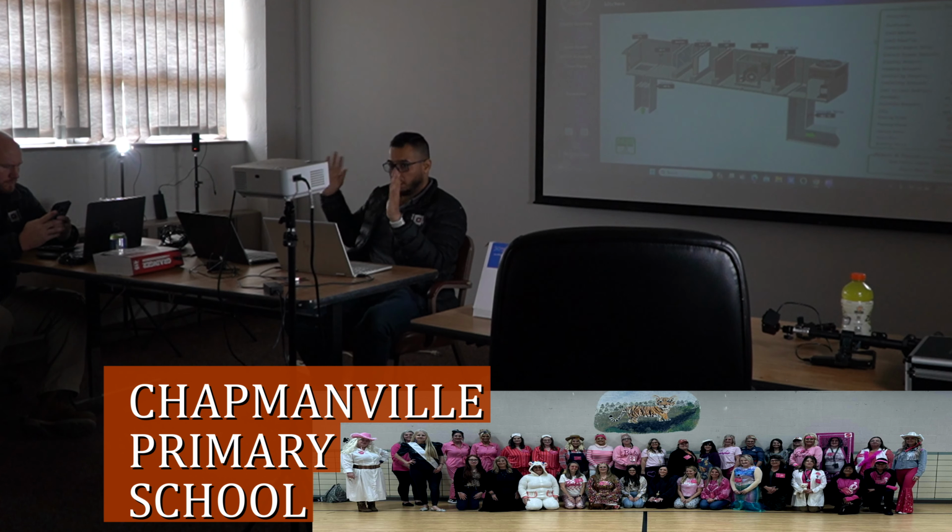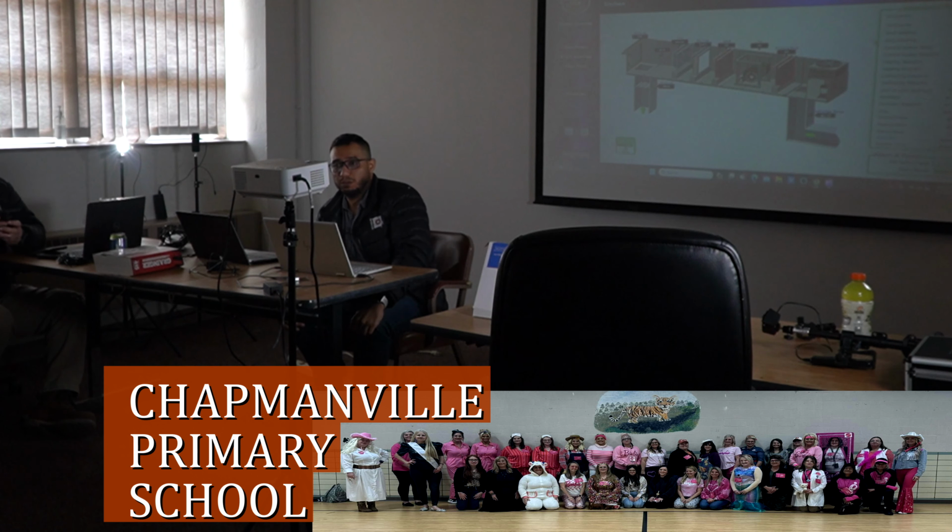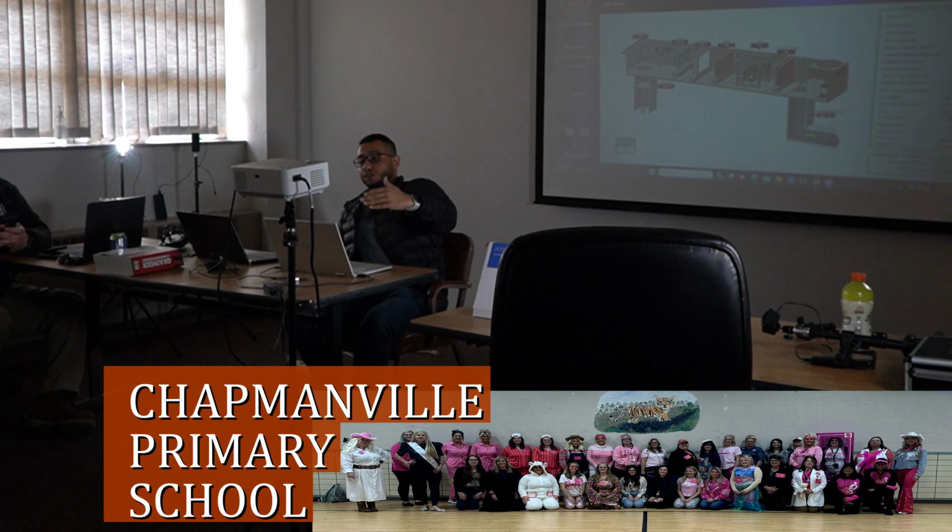What about CO2? Regardless, because you picked the summer mode, right? So if you have an occupancy day, you probably want to take that summer mode off and let it roll as a normal day. So that's the give and take, because you want summer mode to keep your equipment out of the fresh air, or the outside humidity and so on. At the same time, you probably have an event, right?